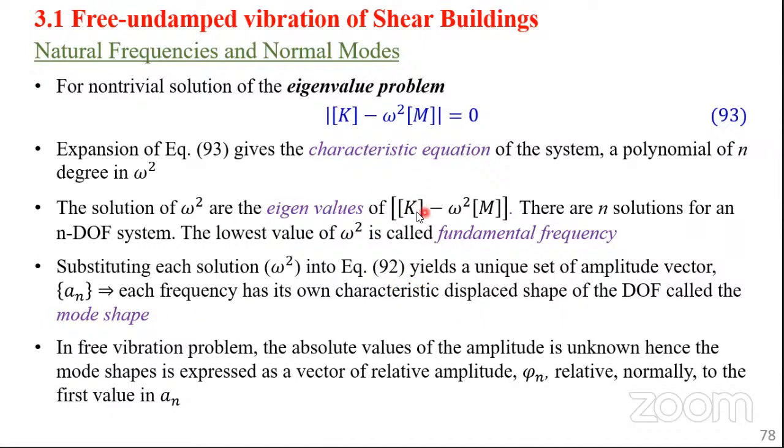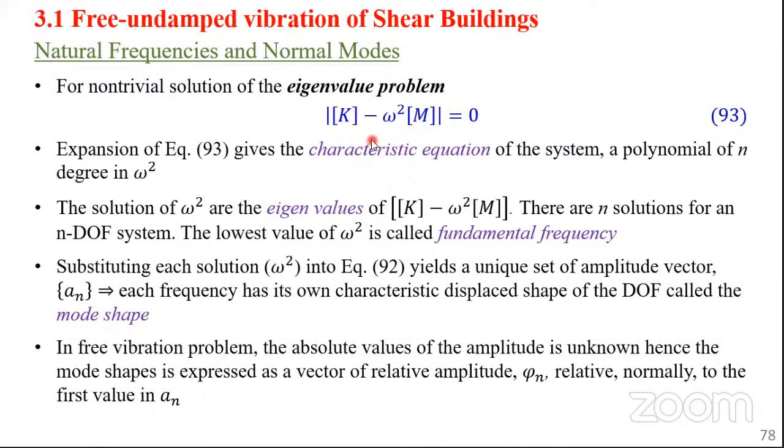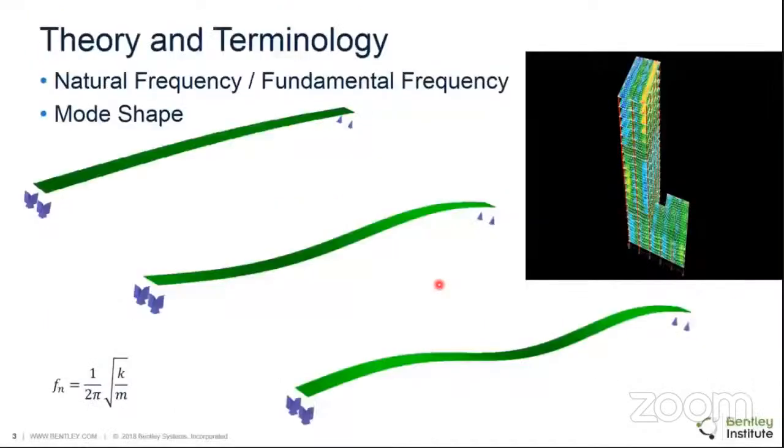The mode shape is obtained when you solve the eigenvalue problem. Yeah, we are solving these eigenvalue problems. So we solve by getting the eigenvectors, which are the mode shapes, and then the eigenvalues that you obtain. These are the natural frequencies. And of course, the last part was explaining the phi n. This was to ensure that we express the mode shape in unitless form. I found it important to explain further on this so that it's not just a matter of going through the course, but also understanding the physical implication of this in a real structure.